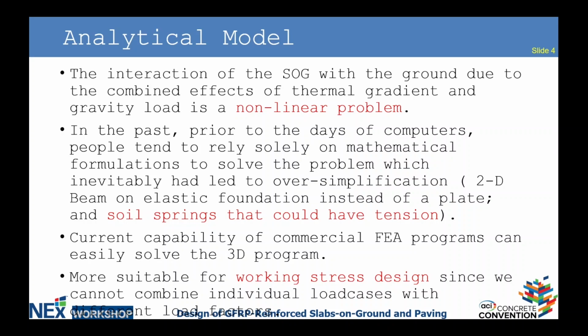So if you're doing a limit state design and you have load factors like 1.4, 1.7, whatever, those are fictitious values that at certain ultimate limit state, from a strength point of view, it may reach that, but you cannot do those combinations separately and try to add the results together after each individual analysis,